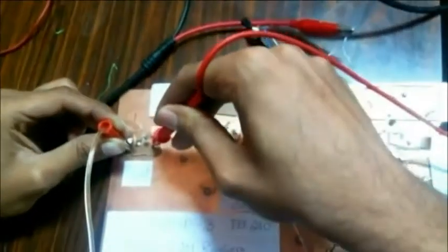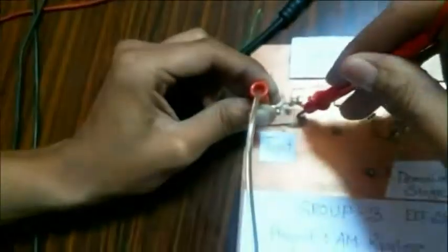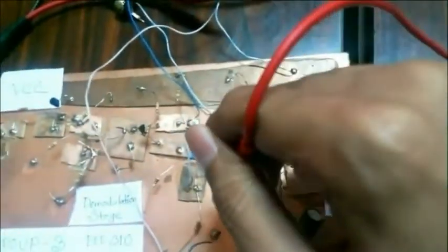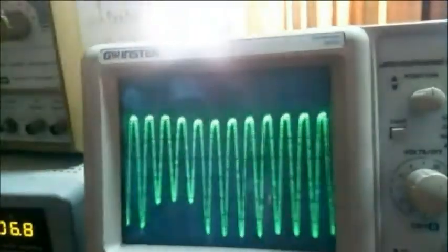Over here you can see the modulated signal. As we change the amplitude, it is changing on the oscilloscope. At this point, after the input, the signal is passing to the demodulation circuit, and you can see the signal has been demodulated to a 1 kHz sine wave. Then it passes on to an RF amplifier stage and a low pass filter, and it is being amplified to this oscillator output.